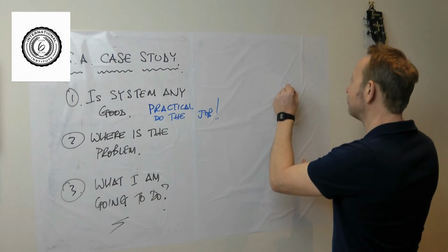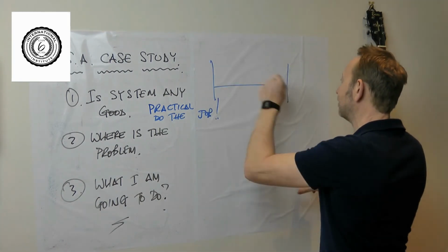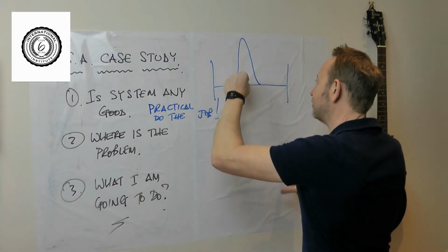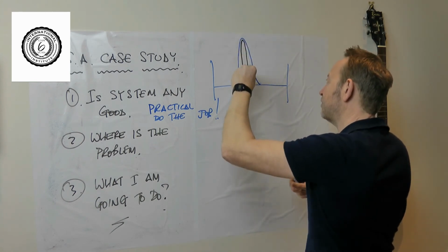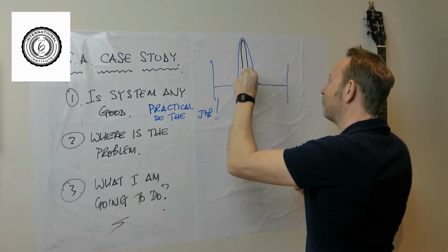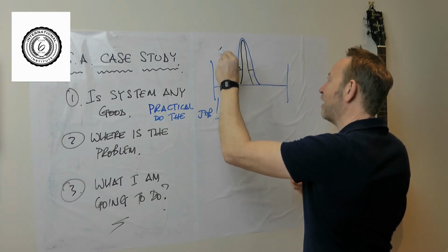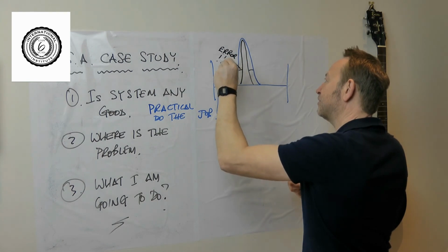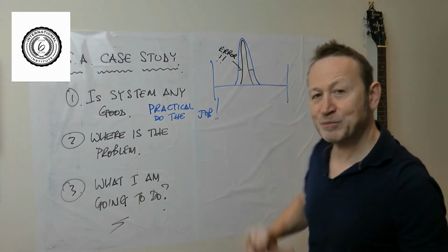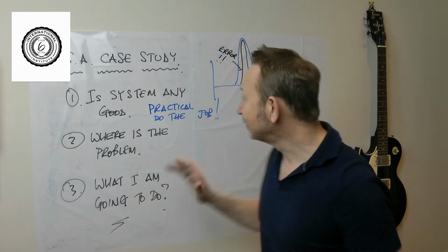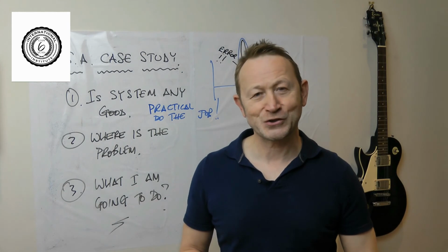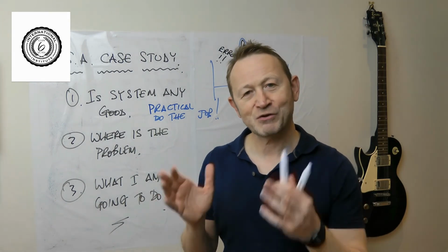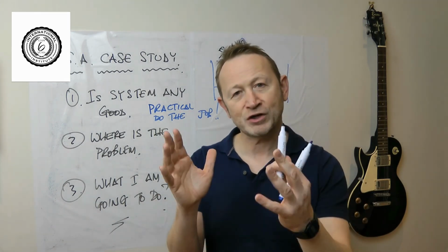If you have a measurement system, if you have a capability, the first thing you should always do is a CPK. So if you do a CPK and it looks brilliant, but then you do the MSA and it's terrible, so you've got lots of error here, people tend to panic and go, well, I've got a very poor measurement system. Doesn't matter. You've got a great CPK. Your measurement system's not going to influence the situation at all. So it doesn't matter. You've got to use MSA in the right context.